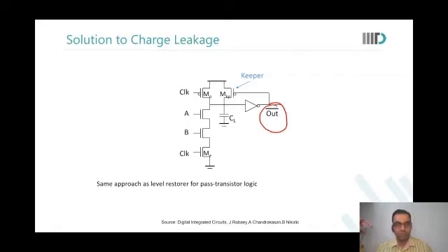Sir, one more small question. In the project, we are supposed to place our load at this position only, at the input before the inverter, the 25 femtofarad which we were talking about in the domino logic? I just answered this question, no? Not necessary. In fact, Tarun asked exactly this question. I said no, you will have to put it on the output of the inverter. If you have static gates following it, then it can be different. But if you have dynamic gates following it, it has to be on out bar. Okay, sir. Understood. Thank you.